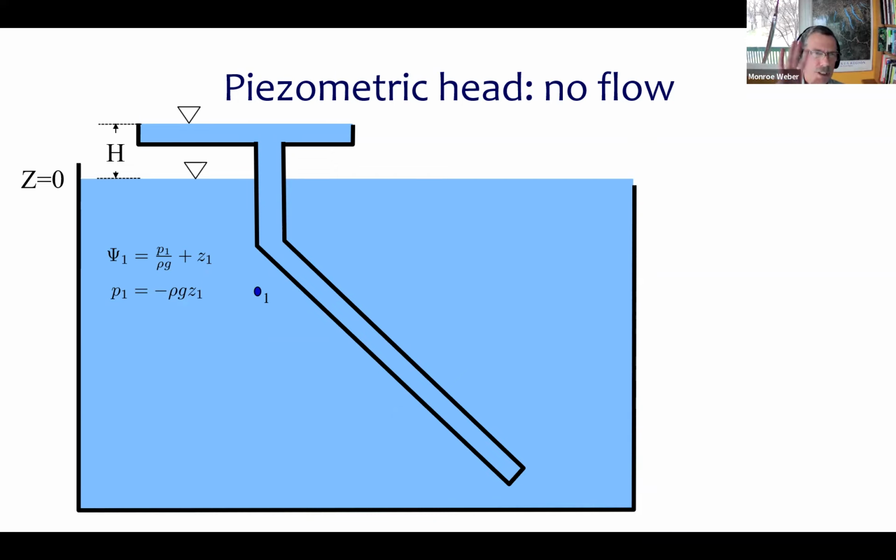If you want to go into real detail, you would have to think extra hard about what happens when you have density differences inside the lake. So for right now, we're ignoring that just to make our lives easy, okay? We assume a lake full of water that's all the same temperature, like it is right about now. So the piezometric head is 0 everywhere in the lake, which means that there's nothing moving the water around except the wind that's pushing it on the surface, but there's no pressure or piezometric head differences driving water flow in the lake.